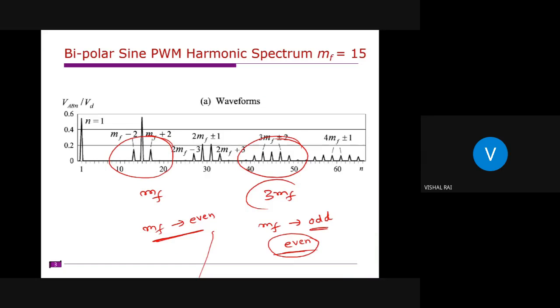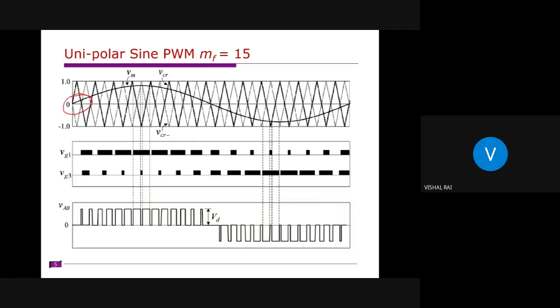All these converters are fed to a transformer, right? When you give some DC offset to a transformer, what could be the result? It will change the flux waveform. The magnetizing current and the flux will increase, and the transformer core may be saturated. To avoid all these problems, we normally eliminate these even order harmonics. So we need to select carefully to avoid that, right? Clear?